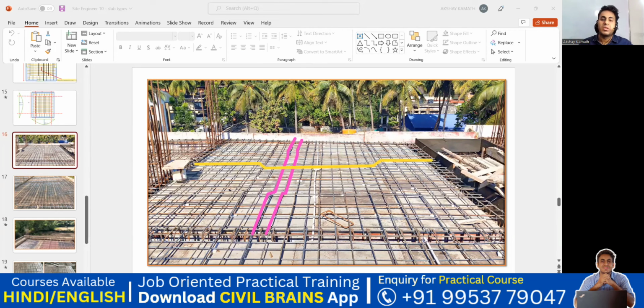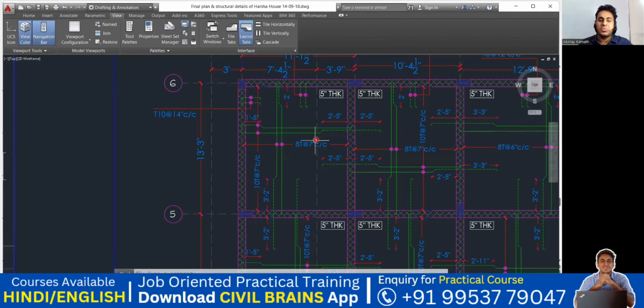So this is my two-way slab, and this is how my reinforcement will look. Whatever reinforcement you're seeing, practically those things are given here. Now you got an idea. Now if I try to draw the same thing here, you will get an idea. We'll start from here. You brought a bar here, you gave a crank, and you took it to the top. Next, you brought a bar from here, you gave a crank, you took it here.